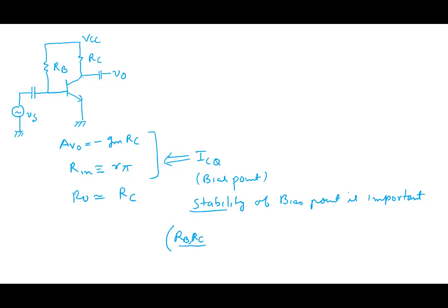They're not exact, especially when you're making lots of amplifiers. In one case you may get a resistor of 1K, in another 0.9K, in another 1.1K. So there's a tolerance associated with these resistors, which will cause the bias point to differ from one amplifier to the next.